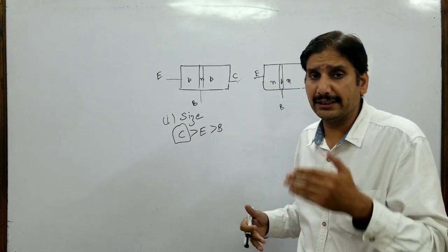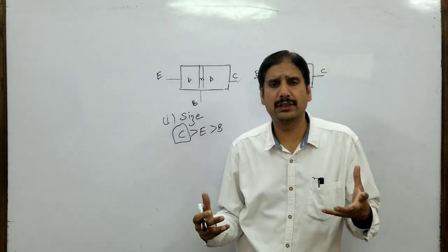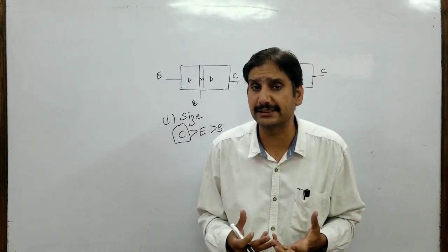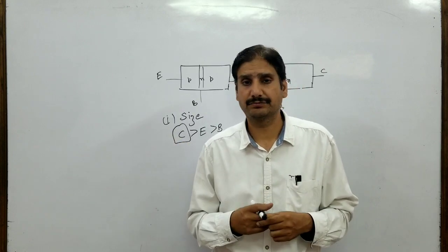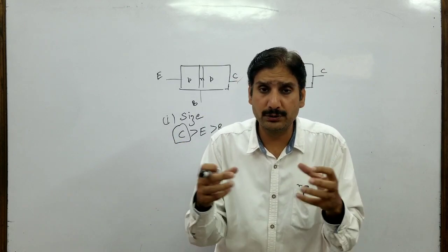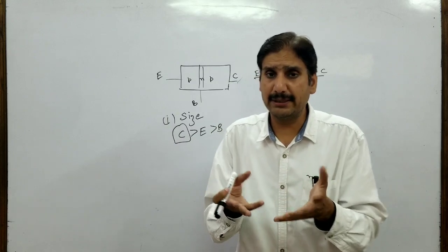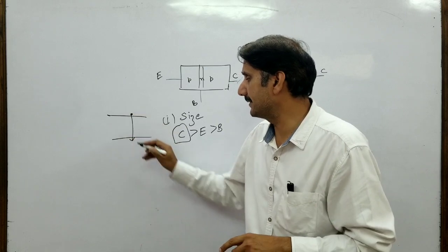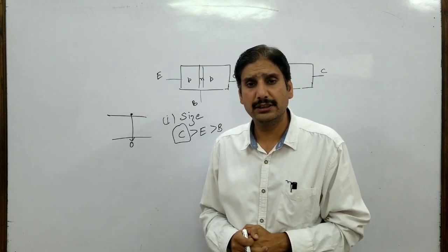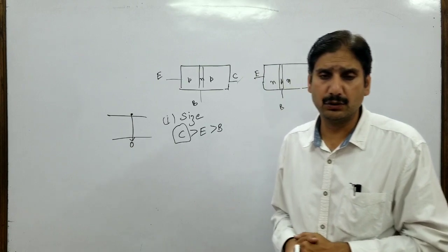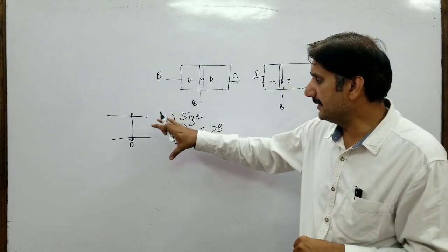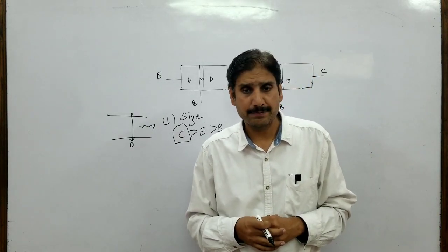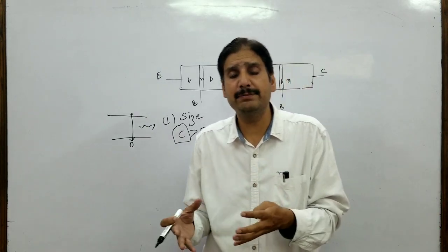Secondly, during the working, we'll see that if not all, then more than 95-98% of the electron hole neutralizations take place in the collector region. And as an electron hole neutralization takes place, some energy is emitted. You should understand that electron hole neutralization is nothing but de-excitation of an electron to a ground state or a valence band hole. That means some energy would be emitted whenever an electron hole neutralization takes place, and that means all the heat is being produced in the collector region.